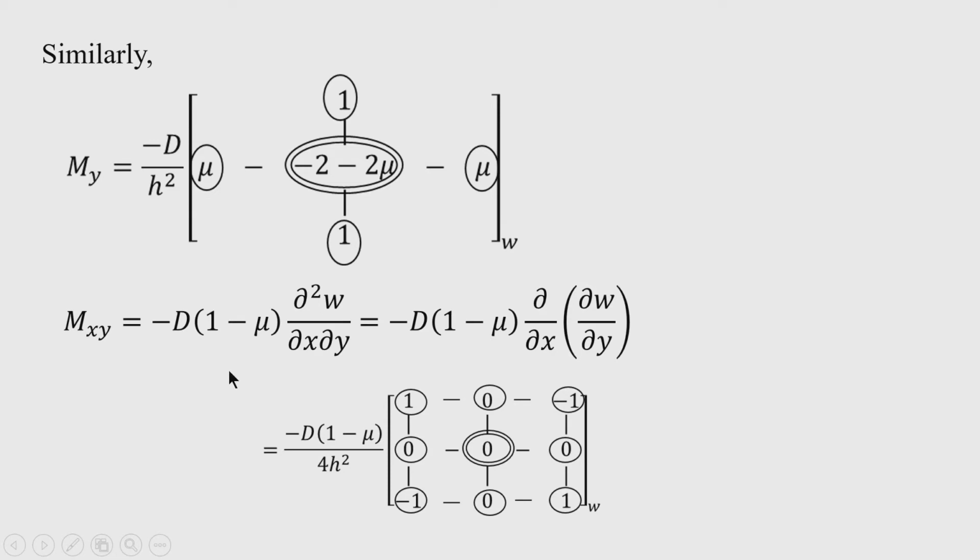That is very important for the free edge condition, because for a free edge, you know that there are three conditions that have to be equated to 0. What are these three conditions? One condition is that the bending moment is 0, the second condition is that the twisting moment, that is m x y or m y x, is 0, and the third condition is that q x or q y, as per their edge location, is 0. So, there are 3 quantities to be equated to 0.